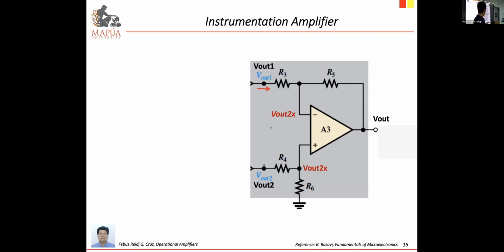Okay, so in this example, the feedback is at the negative. Right? So current along R3 will become current along R5 and the current into the op-amp. So our equation will be IR3 equal to current along R5 plus IN. So IN is 0.